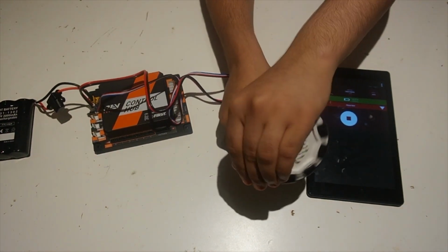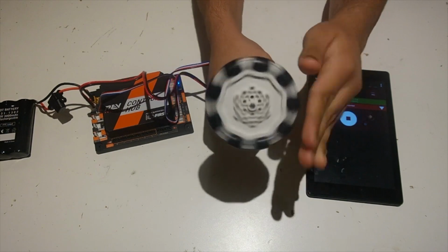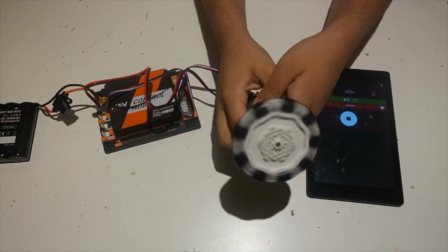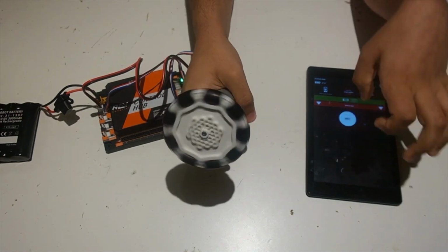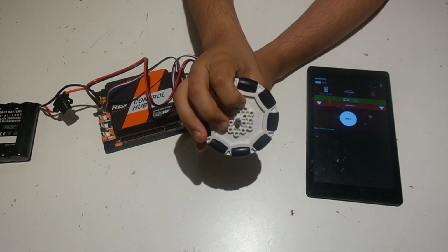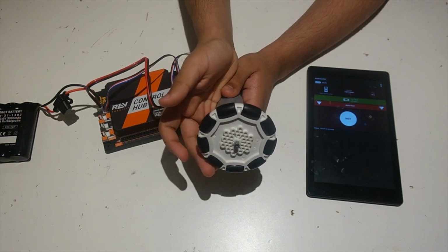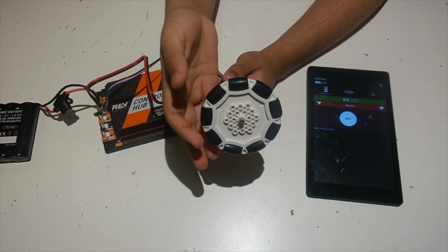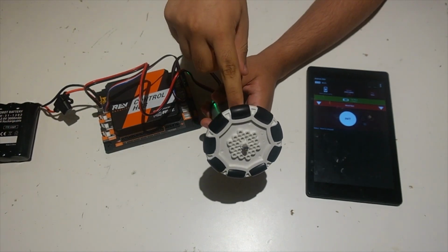If I try and give it resistance, or I try and stop it, nothing. It just continues running. Nothing happens. So you can see if I try and stop it, all it does is continue running in one direction, setting power to 1. Nothing else happens. And that's what run without encoder is. It just does what you ask it to, where it just sets the power to whatever you ask it to. And yeah, so you can set it between -1 and 1. This is how most of your gamepad input and your drivetrain controller is going to be using run without encoder.